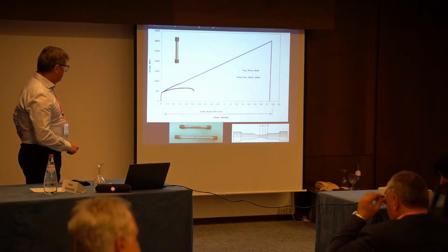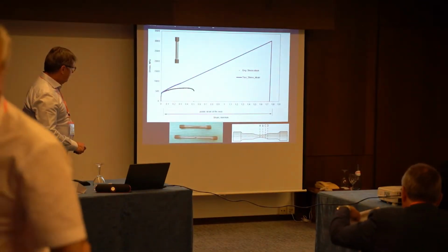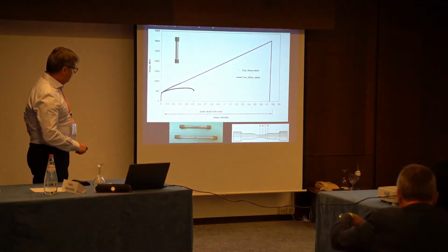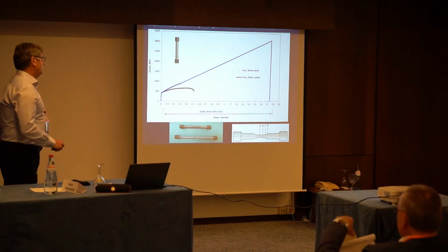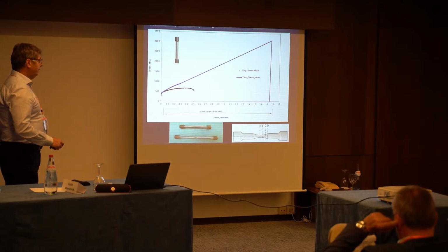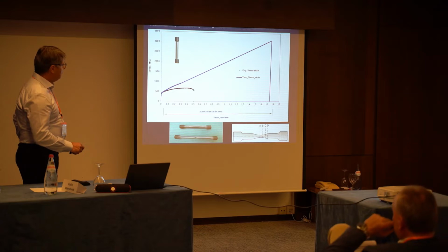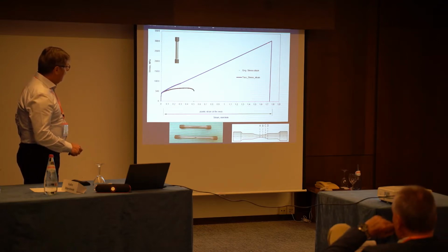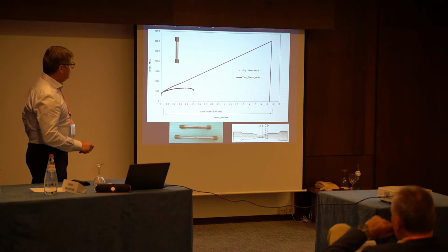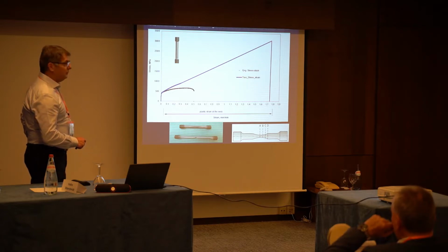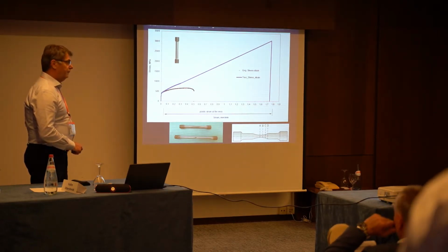You have the yield point, and here the maximum tensile stress, and then of course the necking, and then the failure. The true stress diagram looks like that because you consider the break points and this tension, and you get that the fracture stress is more than 1,000. But of course, the yield point for engineering is here.